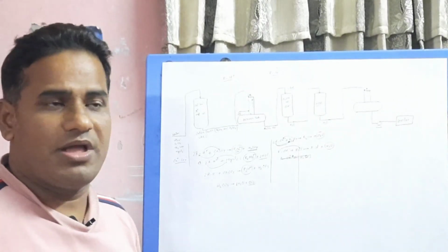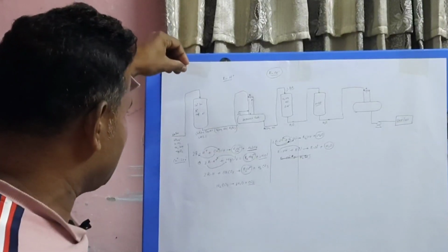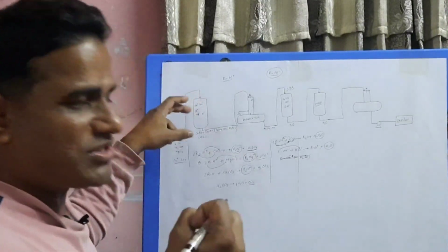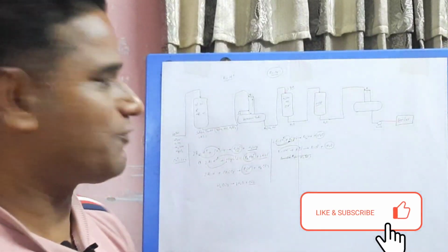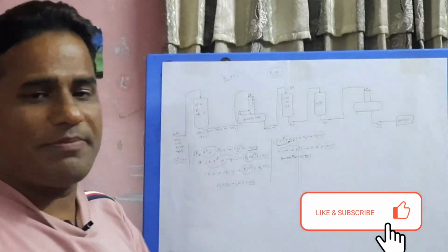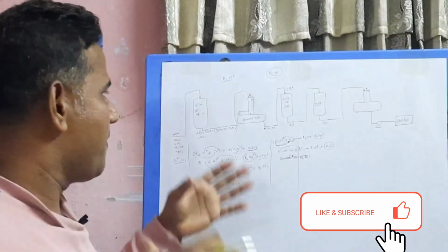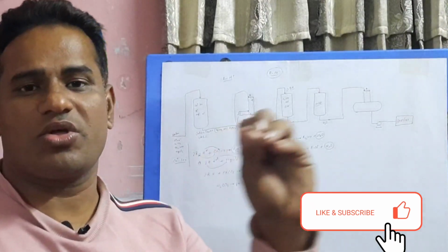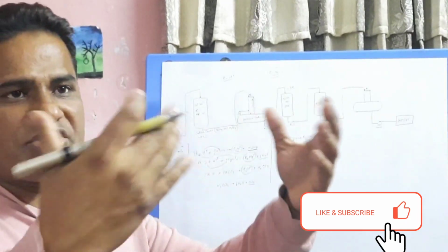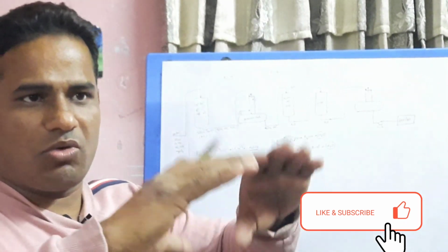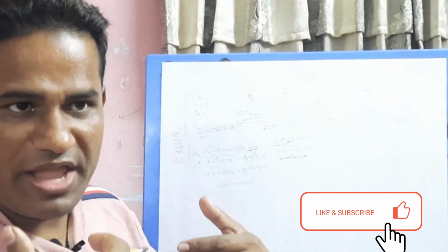What will happen then? When this salt or hardness passes through the exhausted resin, all cations and anions will pass through the cation tower. At that time, what will happen? The whole system will come down, and these cations, positive ions and negative ions will enter the boiler. If they enter the boiler, what will happen? The boiler tube will burst, corrosion will happen, and the full system will become abnormal.